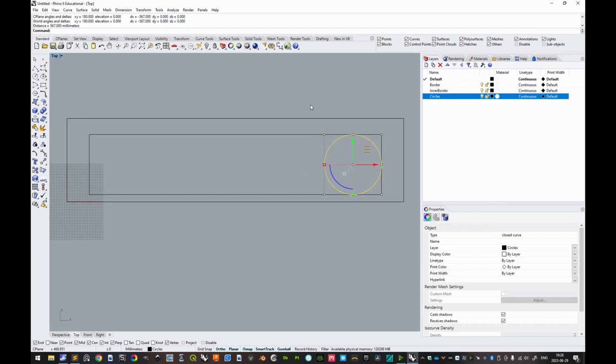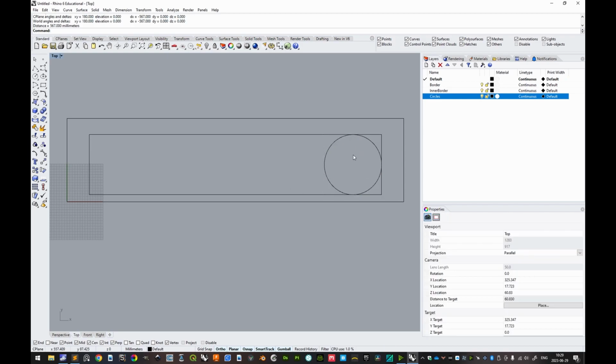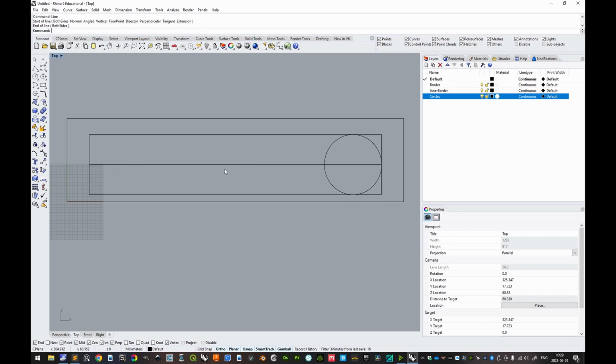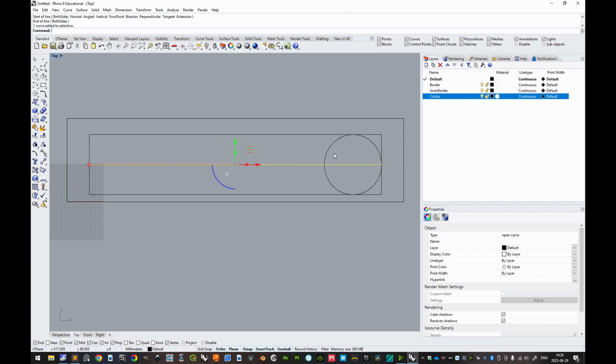And with that information, we could actually do like this. We could create a line. I'll first click in the void to deselect, and then I'll type line here. And then we can go from this point to the other point here. Very good. And having selected that, we can type divide.